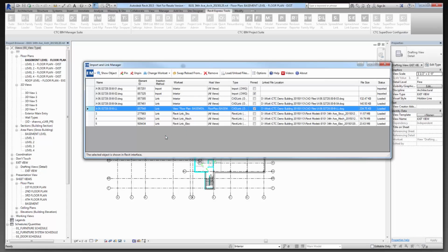So there was a question that popped in a moment ago that said, what if I don't have the original DWG that's being imported? Can I have this tool create one for me? And the answer is, I believe, no, you cannot. This doesn't author a DWG. It's just going to let you path to one. So you would have to have some variation of an original DWG. Now, you could probably take the DWG that's an import.